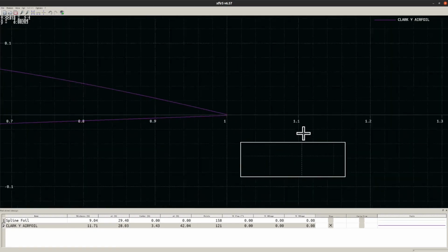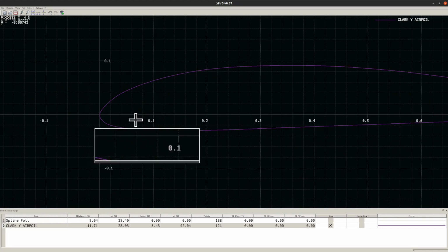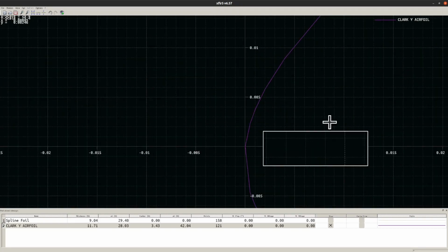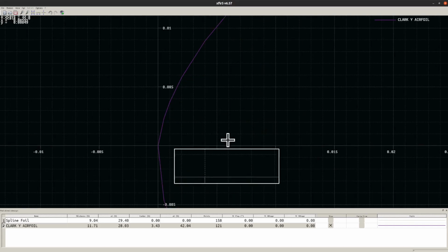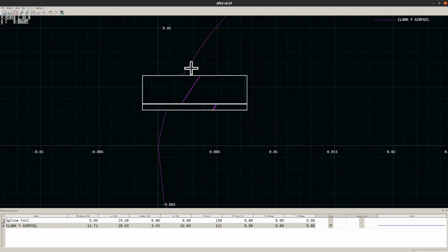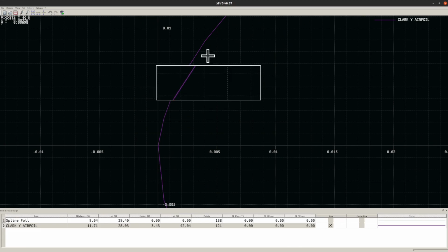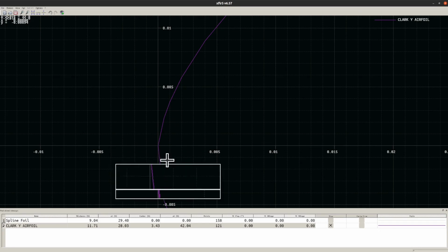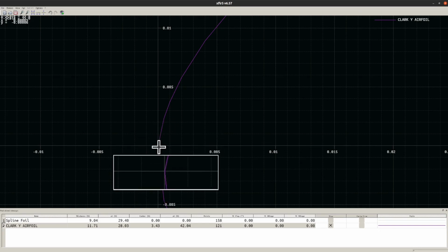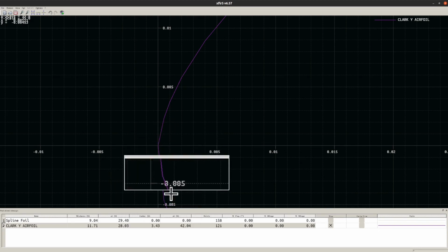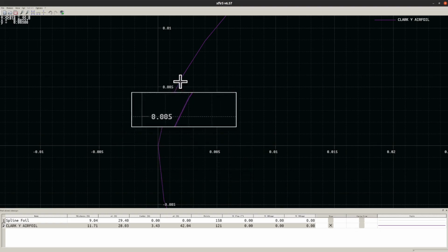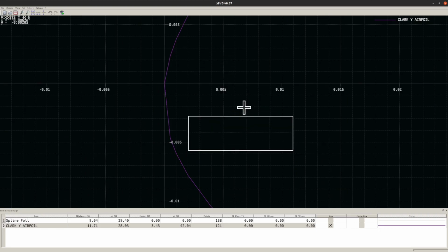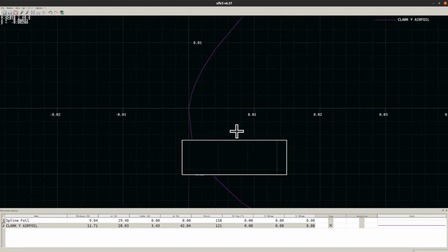And then let's look at the tip. Now as we zoom in here on the tip, you can see that there's various line segments here. So it's a little bit rough up here at the nose. And in fact, at the tip at 0, 0, it's very rough. You can see that this line here goes at a pretty sharp angle, and this line here goes at a pretty sharp angle. Whereas all these others aren't as sharp. Well, you're going to see that causes a little bit of a problem here in a moment. Let me zoom back out just a little.